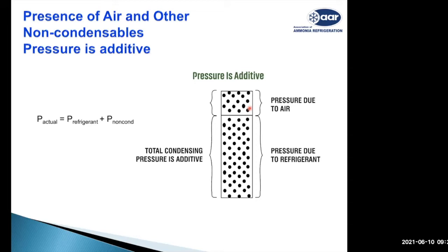It means that if you have different things in the refrigerant and ammonia, such as air, also called non-condensable gases or foul gases, which consist of nitrogen, hydrogen, and some components from the oil, because we are using synthetic or natural oil, they definitely have certain paraffins and other items.